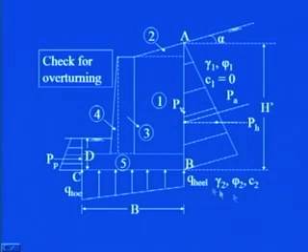Then you see here, below the base slab of the wall, the soil properties are gamma 2, phi 2, C2. However, the backfill which we have assumed to be frictionless, C1 is equal to 0. So, only the shear strength parameter phi 1 will be there in the picture, and the unit weight of the soil. And here, we have already assumed that the failure is taking place along this AB face. The depth of this AB face is H prime, and this PA will be acting at H prime by 3 from the bottom of the wall.